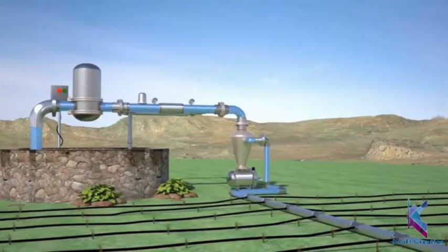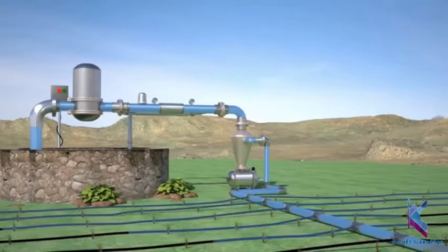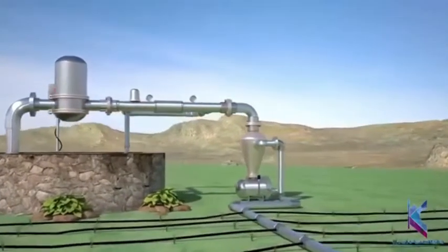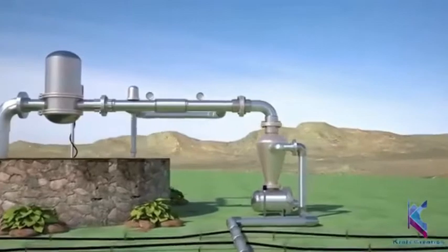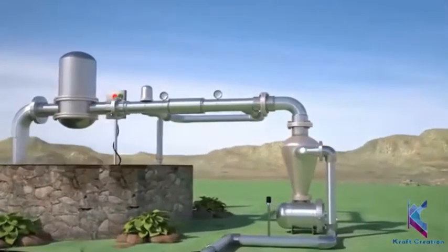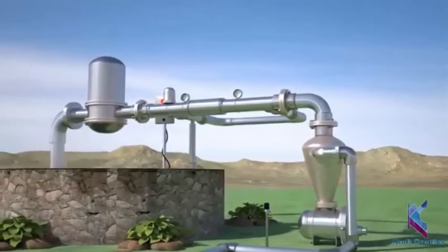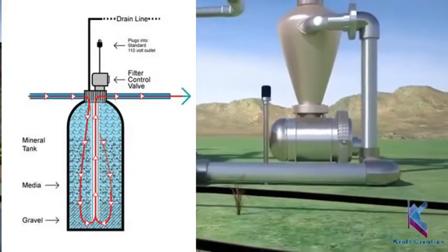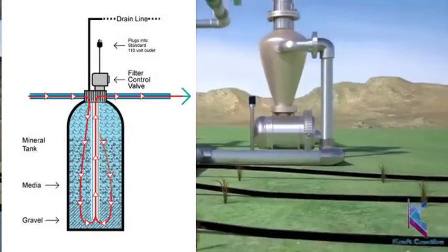A control system regulates dosing to the drip fields. Most systems utilize a control panel to implement time dosing to the fields. This allows effluent to be distributed throughout the day in even doses. Control panels can also control automatic filters, backwashing, and field flushing.